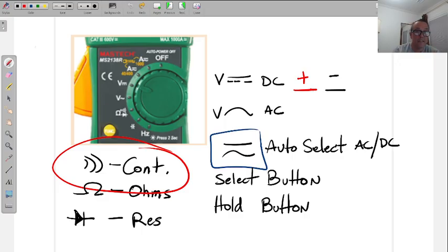You should have a rough estimate of the amperage that you're going to be checking, because you see the number on the breaker. So you just want to make sure that you are using the 40 when it's less than 40, and then using the higher one when you're above it. Now, could you turn it to the 400 and measure 8 amps? Yes, you can turn it to the 400 and measure an 8 amp circuit, or measure 8 amps on a wire. But it's not going to be very accurate. It's going to be off by a little bit.